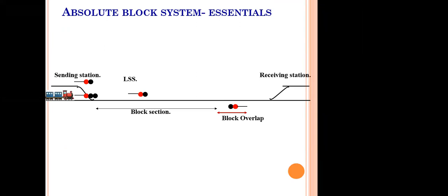US Railway, yes, it uses automatic block signaling on single line. Even on Indian Railways, some parts between Vijayawada to Krishna Canal and Kazipet to Warangal or Kazipet to Kesarghatta, some stations have the single line automatic block system. That is possible, but we are using it under special permissions.